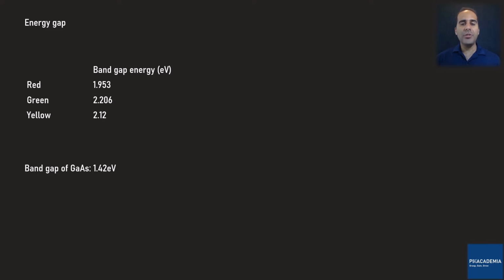Basically, what we can do is manipulate the semiconductor and its manufacturing in a way that we achieve the desired energy gap and therefore the desired wavelength. As an example, let's imagine we want to build a red LED using gallium arsenide. So I need to think about this LED structure. At the very bottom, I have an ohmic contact.